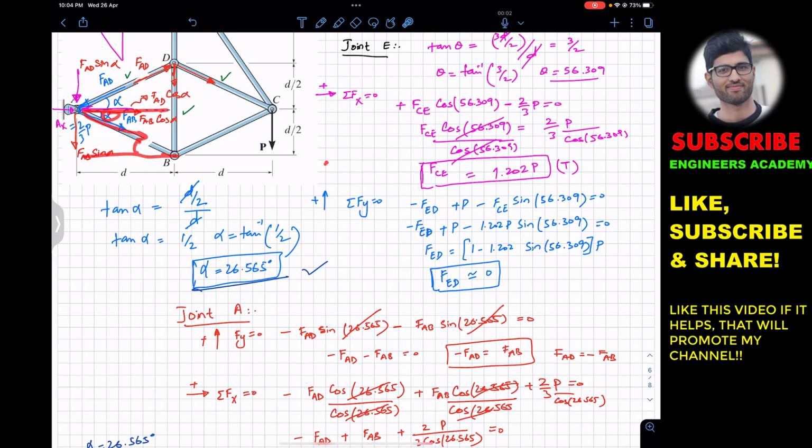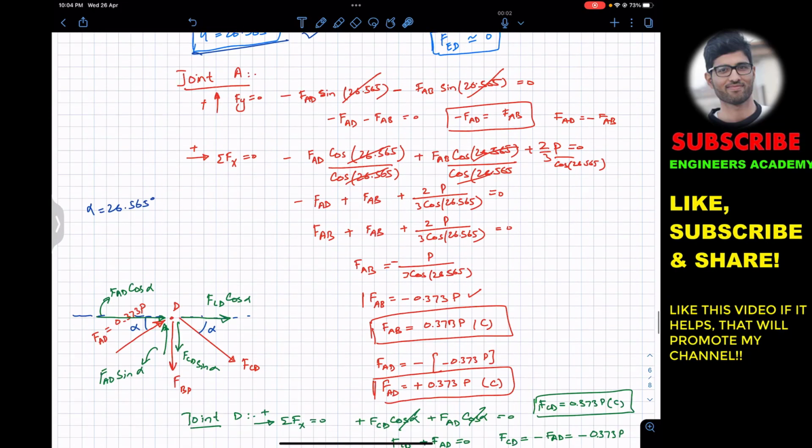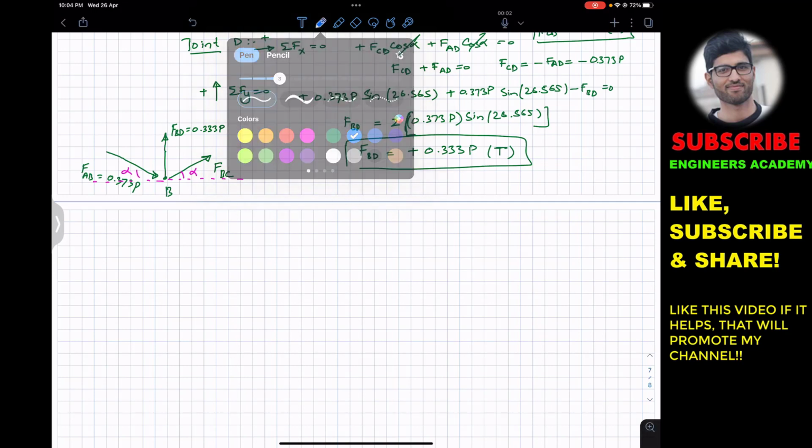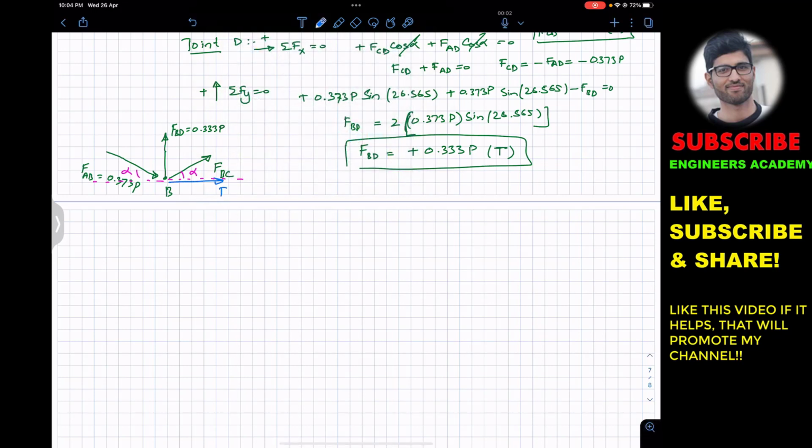If we draw that angle here, both of these angles are alternate angles, so we will have the same angle alpha here, and the same angle alpha here as well, since this is d divided by 2 and this is d. So here we have angle alpha, and here we have that angle alpha, and similarly we can resolve FBC. It will have one component, FBC cos alpha, and this will be the sine component. Similarly, FAB will have one component in this direction and one component in this direction.